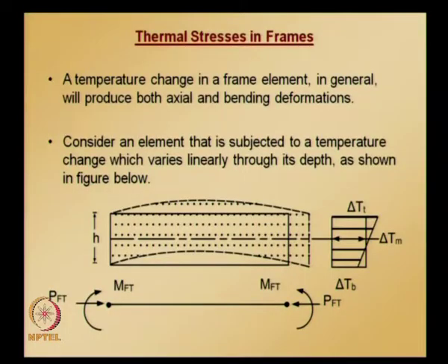In addition, in a frame element axial forces will be developed at the ends, because if both ends are constrained, reactions will be there, and the direction in which these axial forces act is also shown in the figure. Please note that the deformation shown in the figure is for the condition that the top surface temperature is higher than the bottom surface temperature.